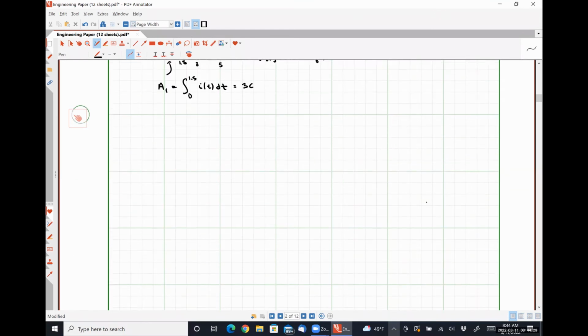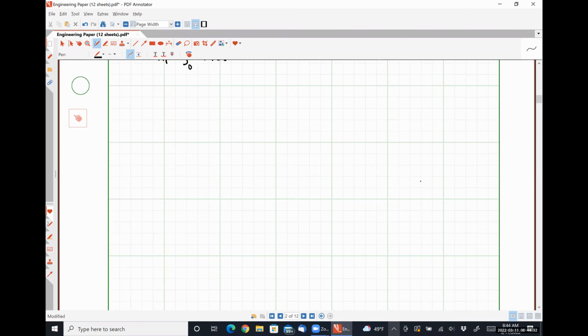Okay. So a current, much like a voltage, actually has 2 components to it. If we had a generic circuit element A, and I said that there was a current of 2 amps flowing through it, again, we have an underdefined quantity. Voltages had magnitude and polarity. Currents have magnitude and direction. So I have to assign a direction to this current. So let's say arbitrarily that 2 amps of current is flowing down through the element.